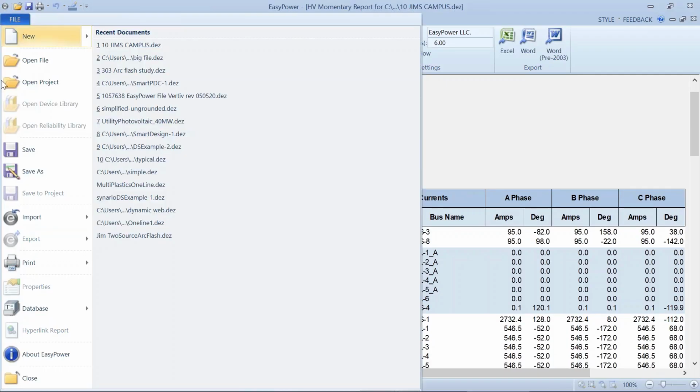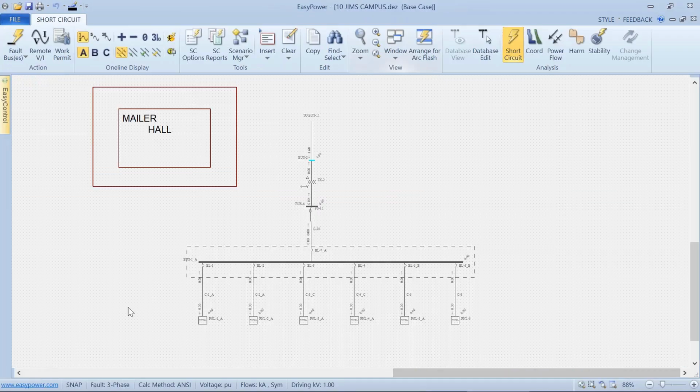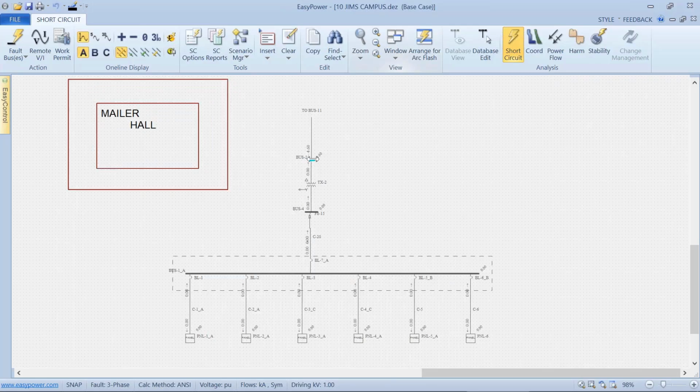particular bus. And again, what this would allow me to do is develop 10 or 11 different one-line diagrams for each building, and instead of having this connection to the ring, have this be a transformer, a utility icon that would give me the equivalent of the short circuit available current at this particular point. The downside with doing that, I mean, it would make it convenient as far as drawing simplified one lines. There are trade-offs involved. If I were trying to limit my bus count, that's one way to do it.